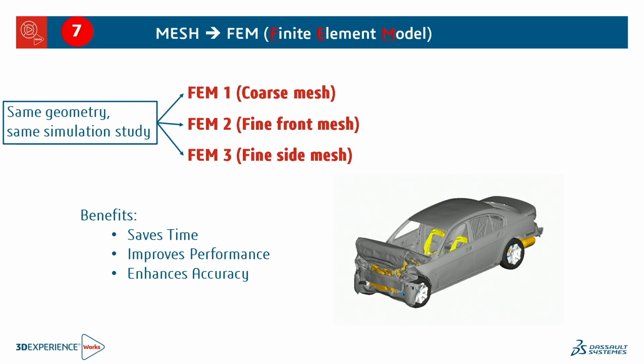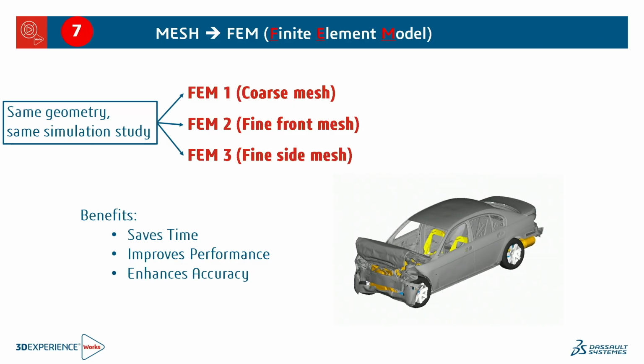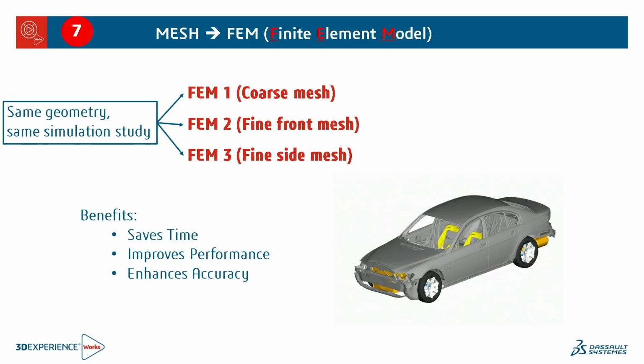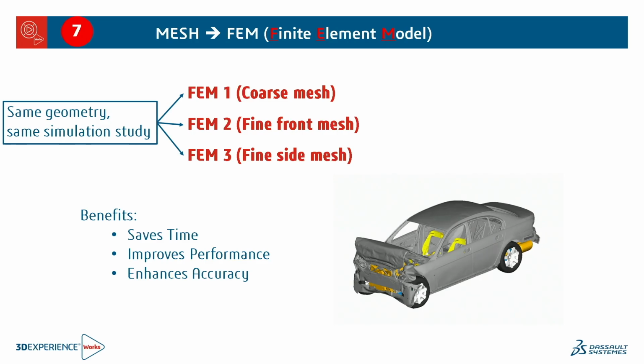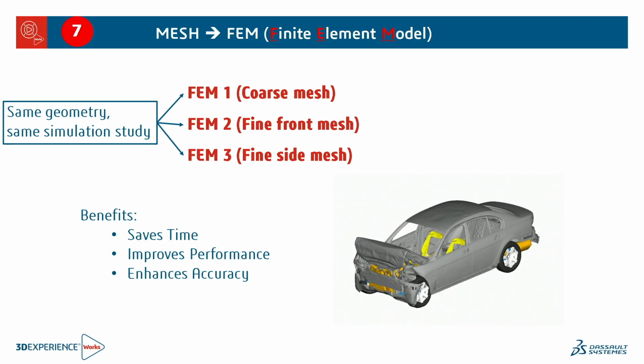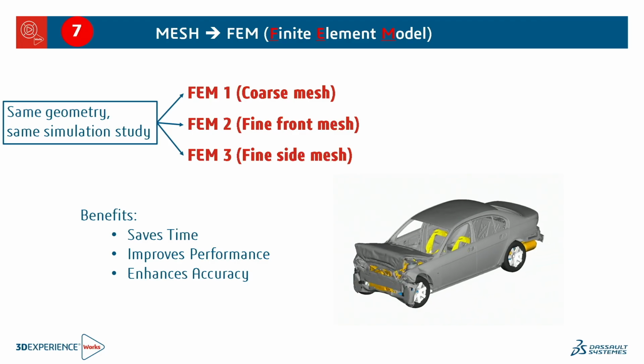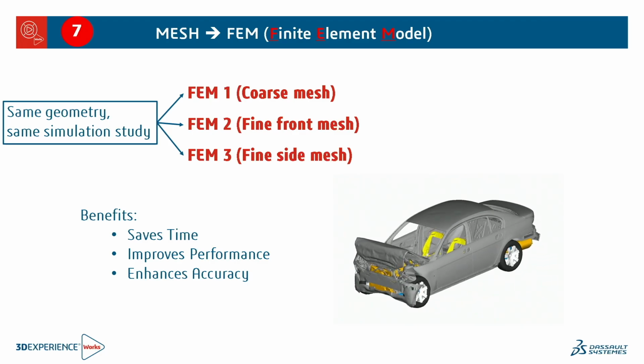You could either just do all parts at once. Like if you only want to do a sweep mesh on every single part, you could just do that all in one. If you want more fidelity, like you want every part that's got a tag of shell to be shell meshed, and every part that's got a tag of hex to be hex meshed, and every part that's got a tag of tet to be tet meshed, you could define those procedures and then just run that through and it would do all of them. So as variable as you need.